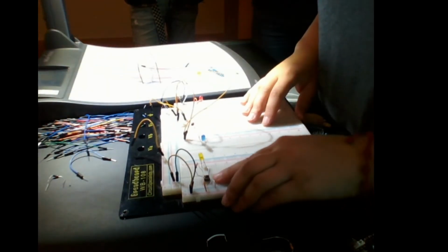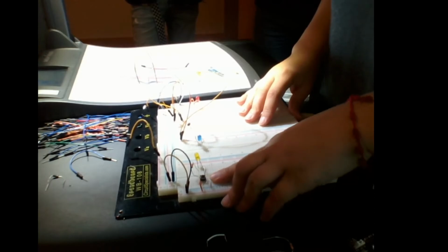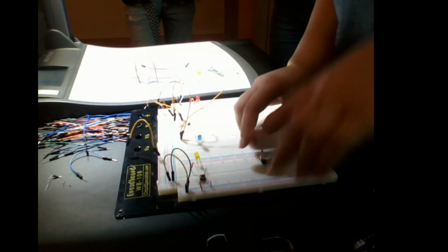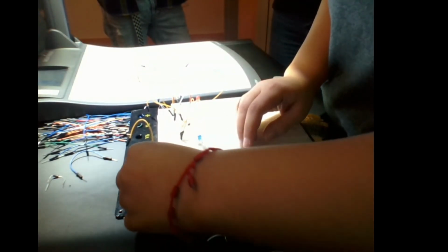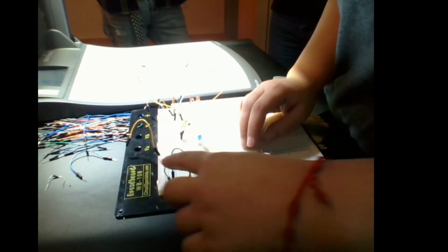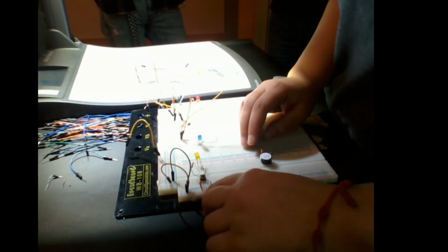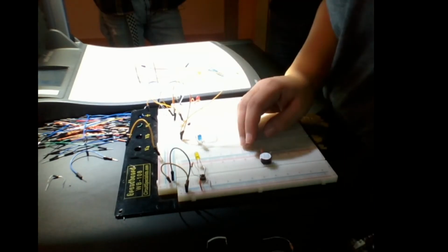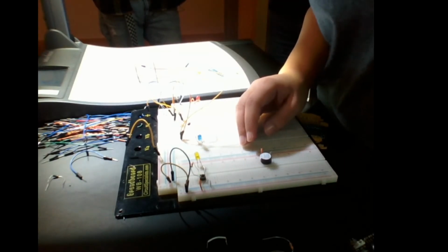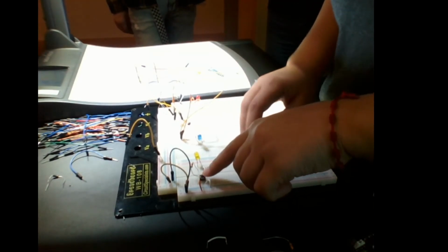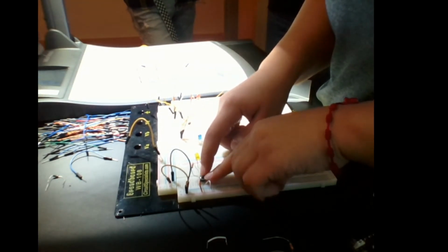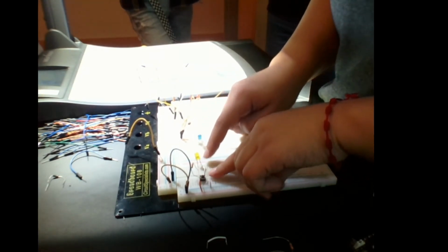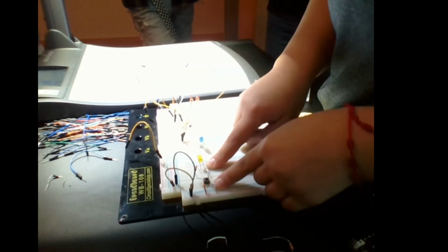This right here is our push switch, just like you see in the image. Looks exactly the same. The way I have it right now is, this is the positive, our plus, our power source, going into our rail. Then it's going into one of the 4 clips that you see on the bottom. Right now it's going into A, and then it's going to run across D, go into our resistor, our LED, and then back through the switch into ground.